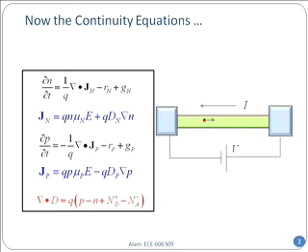So you put the second in the first one. In fact, those two are one equation. And similarly, there is another continuity equation for the holes, and finally the Poisson equation. Now we will talk about the first and the third equation today.